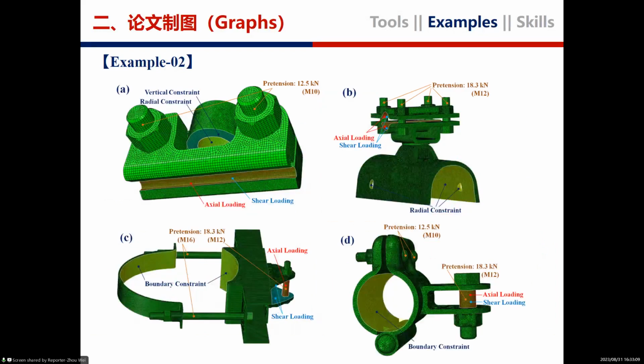We can also use PowerPoint to specify the boundary constraints and the loading conditions for 4 kinds of connection joints by using shapes with transparent colors to strictly cover the shape and area where constraints and the loading were applied. We can show reviewers clearly how those conditions are set before finite element simulation. And this is done again in PowerPoint.